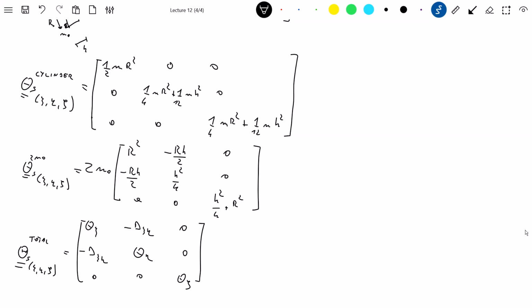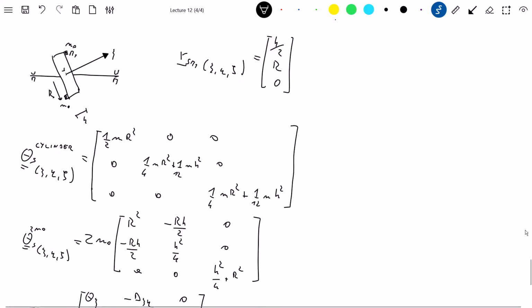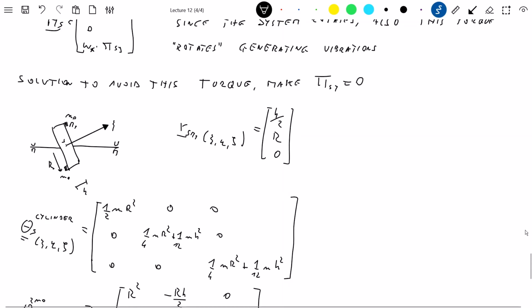So now there are two methods. What do we want to do? This is critical, maybe I was not clear on this. We have this cylinder which is a little bit tilted with respect to the axis of rotation, so we have some force generated which we don't want to have. We want to go to something close to the ideal case. We don't want this dynamically unbalanced system. These two masses will not move the center of mass, which is still there, so we don't want to cause any static unbalance of the system.